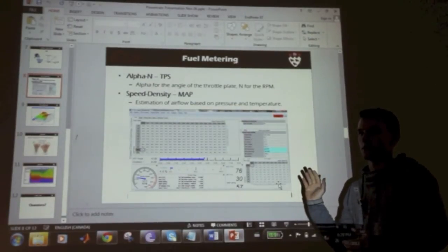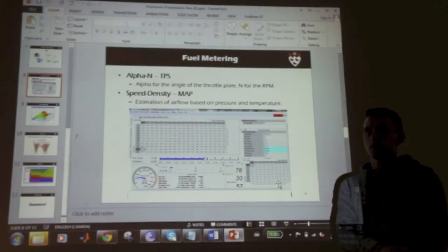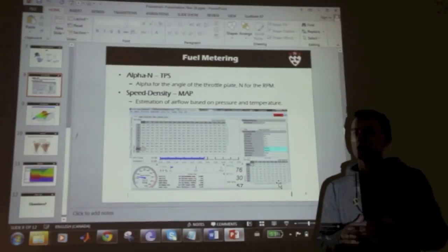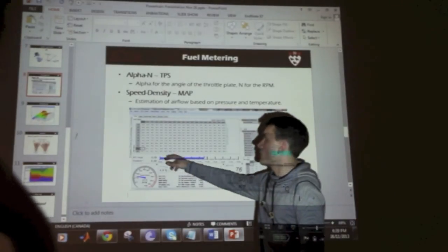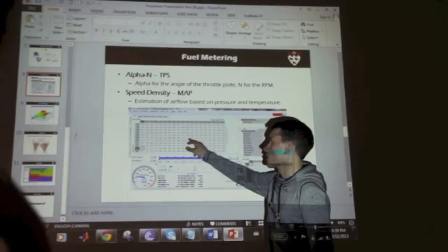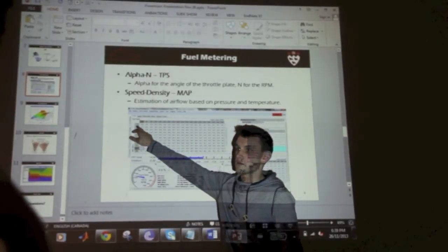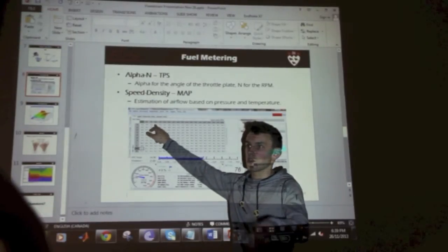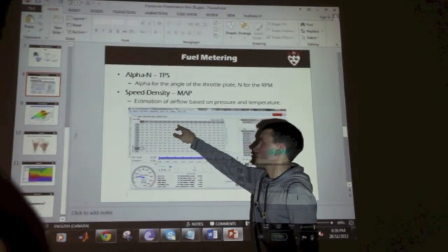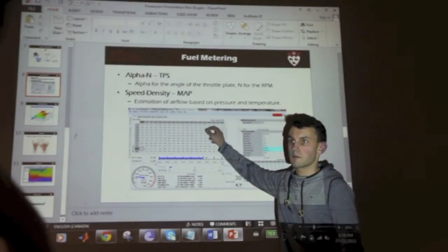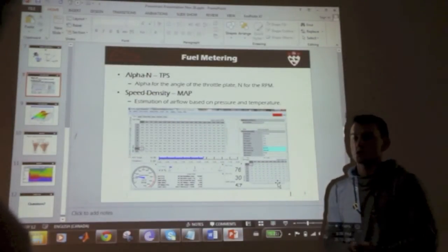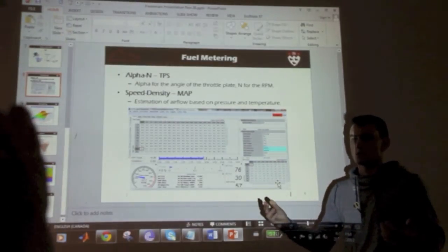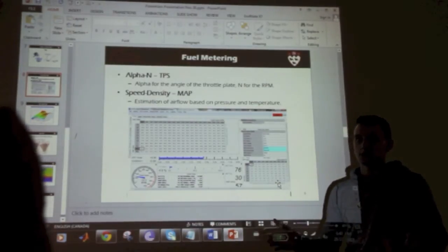Then you set your initial RPM, and then you go full throttle, and the computer running the dyno will adjust the load based on your sweep rate, and essentially allow you to accelerate along one line. So for example, if this is 100% throttle, you start at say idle, 2,000 RPM, you go full throttle, and then it'll adjust the load, so you go directly across the top, and adjust your fuel and your emission that way. And that's how you pull the power or torque curves that you see, it's all 100% throttle.